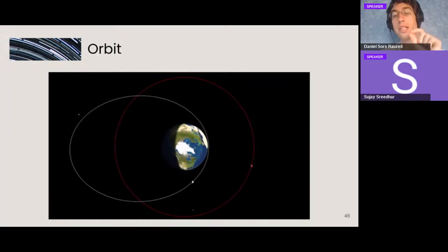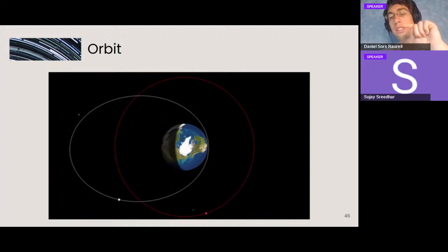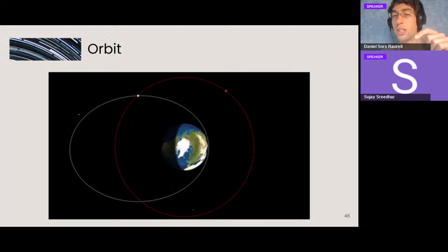You've seen in BAP that there are 6 parameters in the orbit that you can define. If you have chosen the ISS, or if you left it as the ISS, all the rest of the parameters have been frozen because we know the exact position of the ISS. But if you choose polar orbit or sun-synchronous orbit, you will see that only some parameters are frozen. For polar orbit, it's 90 degrees. For sun-synchronous, they depend on other parameters. So you've seen in BAP that this is simplified a bit.